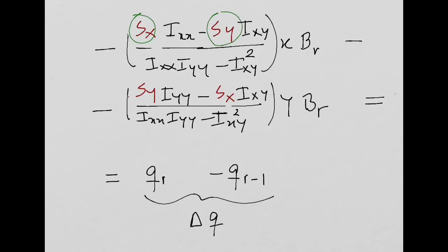That is given in our problem, is the lift, for example, in a wing. What else do I need to know? I need to know the inertia properties, Ixx, Iyy, Ixy, products of inertia, second moments of area. So I know that. That is the characteristic of my cross-section.